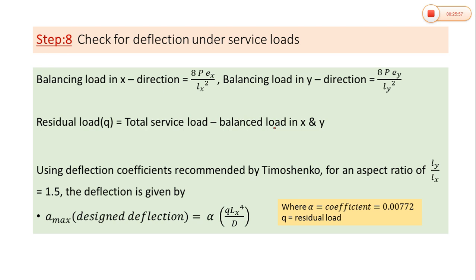So deflection check, many times we are not going to use this deflection check for the slabs, because last year for ST2 two-way slab we haven't used this check. But in the mini projects given in the term work, we need to apply this check for the deflection. So to check this deflection, first of all we need to calculate the balance load.